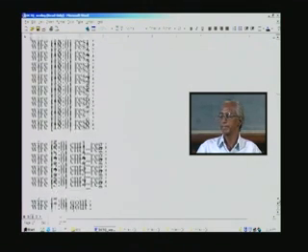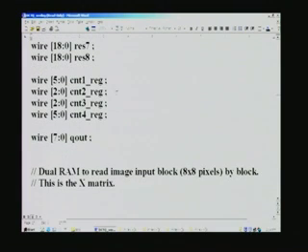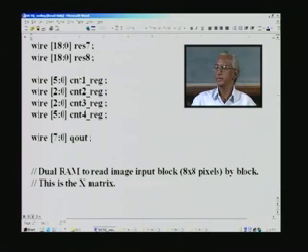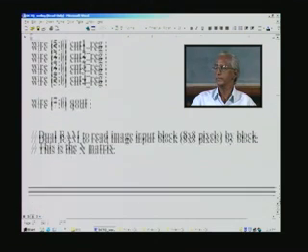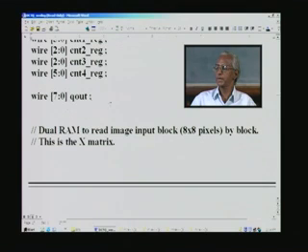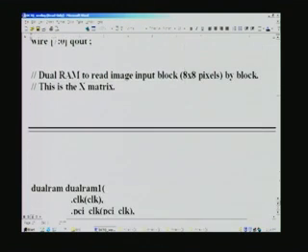and then we will be needing some counters in order to realize address generation as well as addresses for the ROMs, RAMs, etc., which we use in our architecture, and these are all generated in the controller. And this is for the quantization table. We have a ROM whose output is Q out here, and an important thing here is a good design